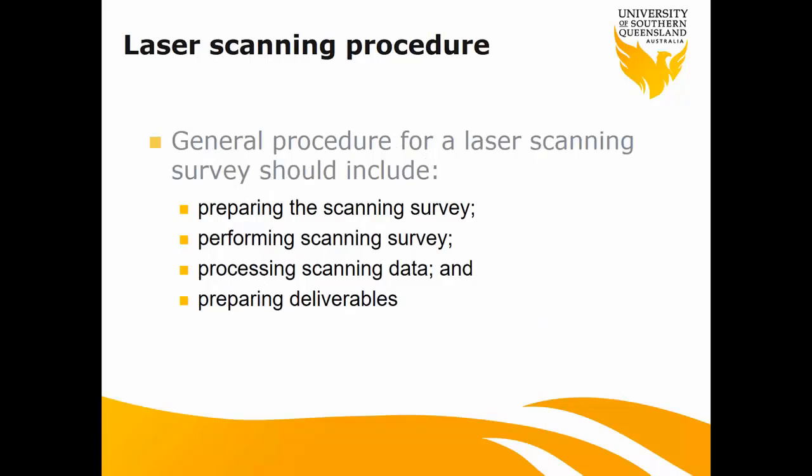General procedure for laser scanning survey. Usually, like any other survey task, it includes preparation for the scanning survey. So we have to know the objective of this laser scanning task. What's the requirement from your customer? Just a detailed survey, 3D building modeling, or any other purpose. The next one is performing the scanning survey.